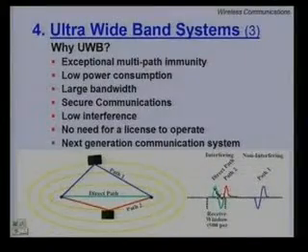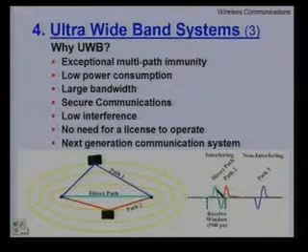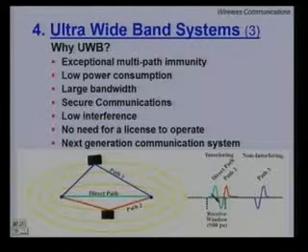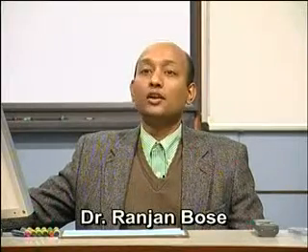However, I am talking only from the transmitted power. Unfortunately, to do signal processing at this high frequency, see, nanosecond, that means if you are doing a digital rake reception, then you have to sample it sub-nanosecond. Your A to D converter must work at that rate, and the A to D itself will consume a lot more power. So those are the design constraints. The power is consumed not for transmission but for processing. So one of the challenges of UWB is to make low power hardware for processing of very narrow pulses.